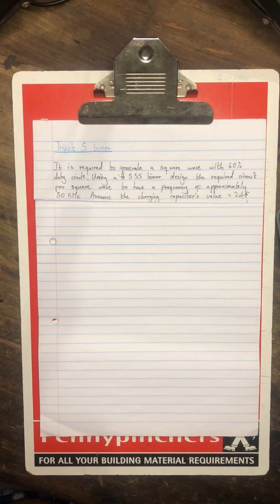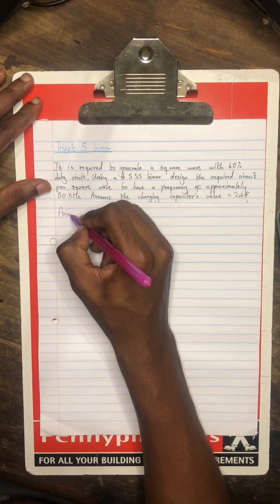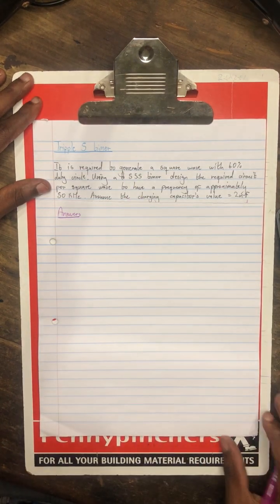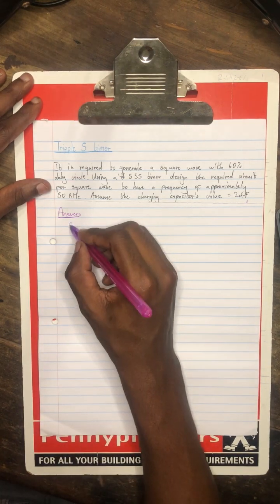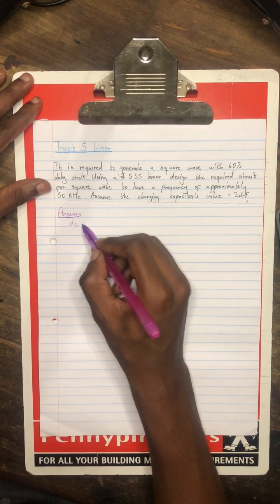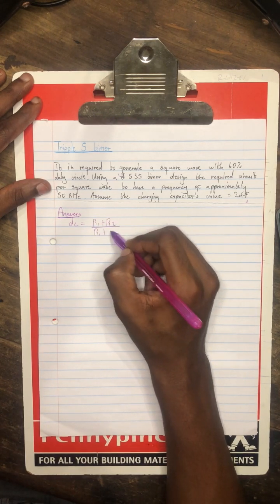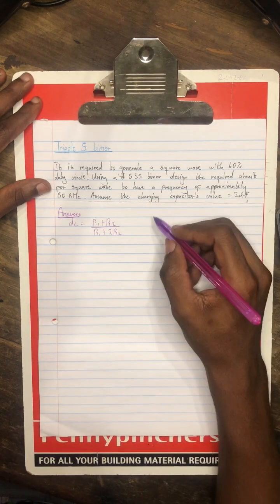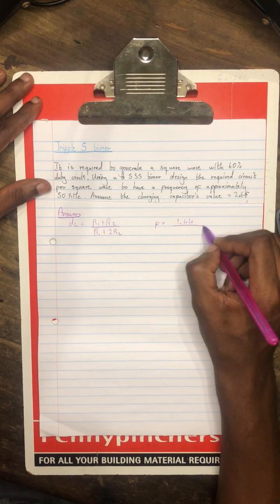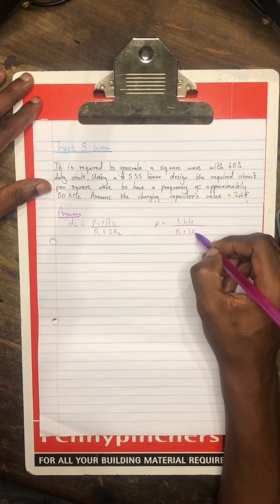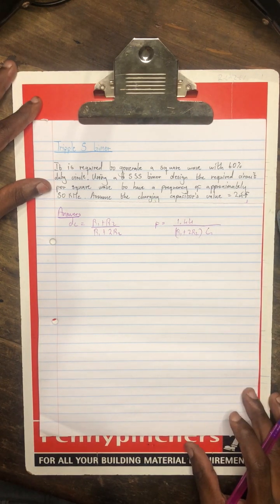So for this we need to answer it, and here are the formulas that we are going to use. The first formula is the duty cycle formula. The duty cycle formula, which I'm going to represent by DC, says the duty cycle is equal to (R1 plus R2) all over (R1 plus 2R2). And the other one is the frequency formula, which says that the frequency is equal to 1.44 all over (R1 plus 2R2) times the capacitor, which is C1.